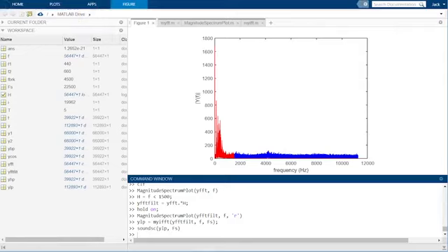Compared to our original signal, much of the noise has been eliminated. The trade-off is that we have also removed some high-frequency content from the signal itself, so the speech does not sound as sharp. Noise reduction is always a trade-off between how much noise can be removed without affecting the quality of the signal too much. Thus far, we have looked at what are called ideal or square wave frequency filters.